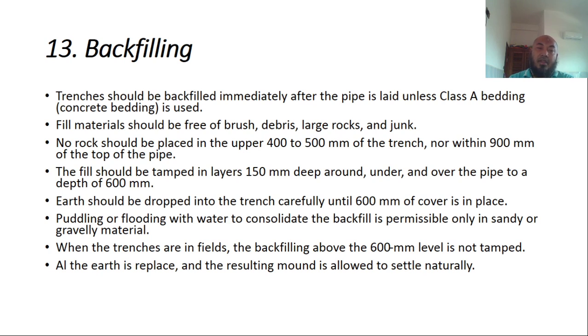The fill should be tamped in layers of 150 millimeters deep around, under, and over the pipe to a depth of 600 millimeters. Earth should be dropped into the trench carefully until 600 millimeters of cover is in place. Puddling or flooding with water to consolidate the backfill is permissible only in sandy or gravelly material.